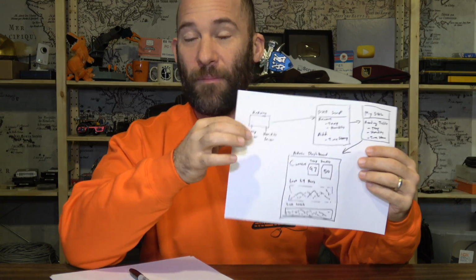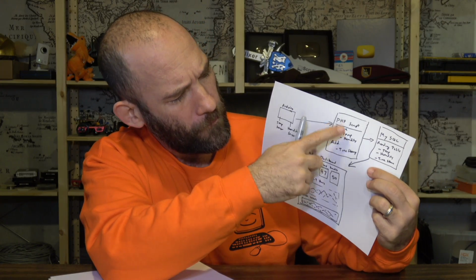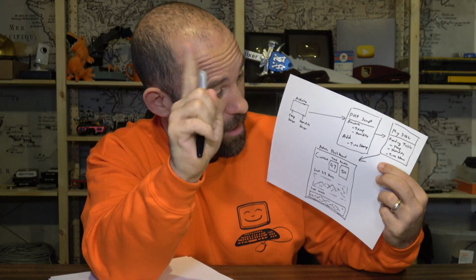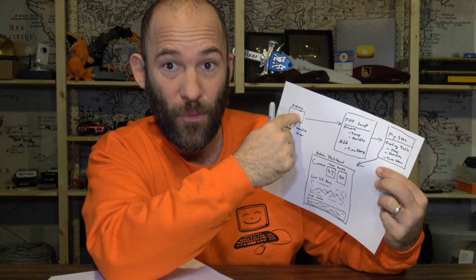Again, we think about the time thing. And this is an important thing to think about in the coding world. This is one of those perfect examples. So in this particular project, we need that timestamp. So I'm going to be using the PHP script in order to create the timestamp that will go into the MySQL database. But that timestamp could come from a real-time clock on the Arduino.